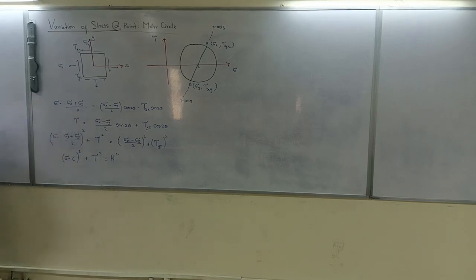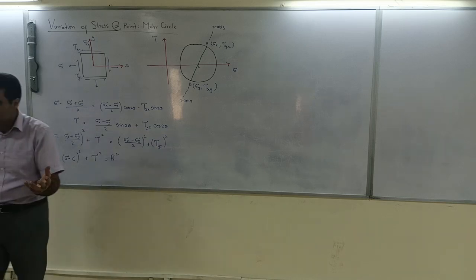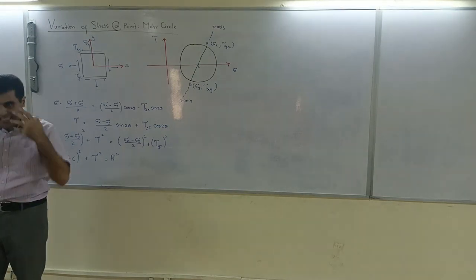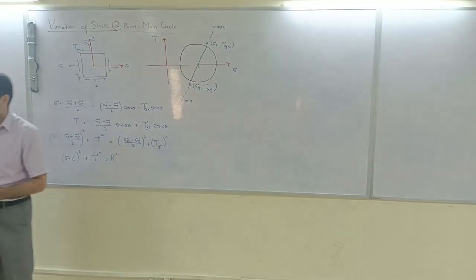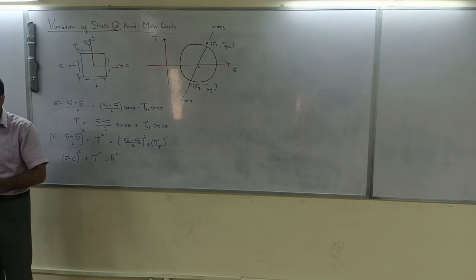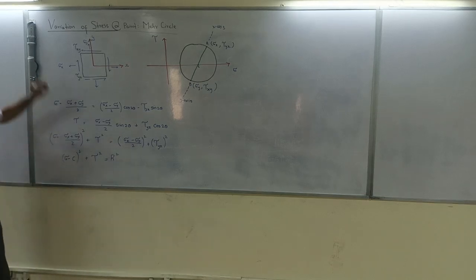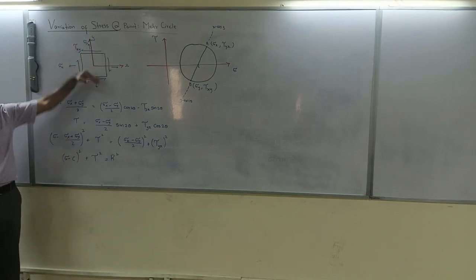So that's the use of this equation. First you normally draw the axial force diagram, the bending moment diagram, and the shear force diagram. That will give you the location where you will get maximum stress. From that location, you pick out that box and draw the stresses.